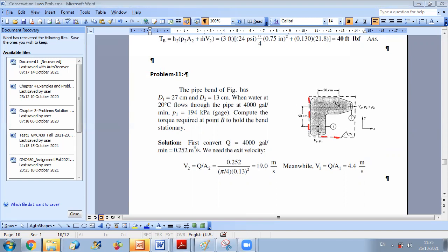Now, what are the external forces acting on it? I have the pressure at section 2. And since the jet is exiting to the atmosphere, here they are just saying that P2 is equal to atmospheric pressure. And at section 1, I am imposing a certain pressure, P1, and they gave me the gauge pressure. They directly gave me the gauge because if they gave me the total pressure, I should subtract from it PA. Why?